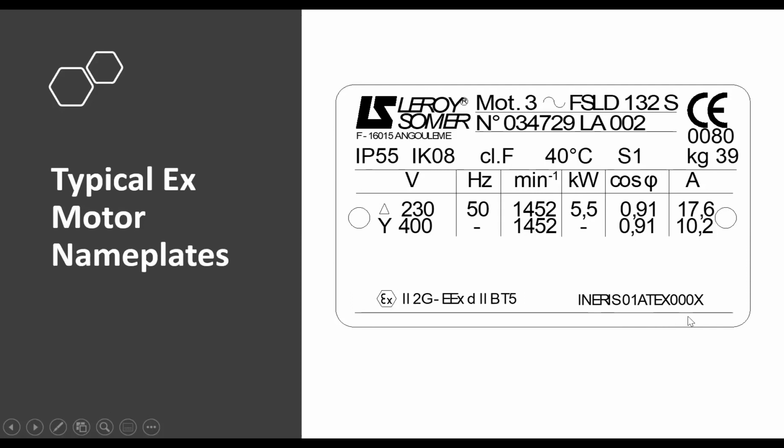If you come on the courses, we will explain to you this piece of information at the bottom here, which will tell you the standards you require to make sure that this equipment still complies. Many people get confused and think that you recertify equipment when you're repairing it. You do not. What the repairers are doing is making sure that the equipment still complies with the standard to which it was manufactured at the time. That is all repairers do. If you want something recertifying, you need to go to a notifying body.